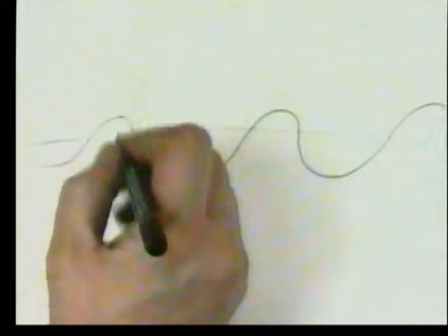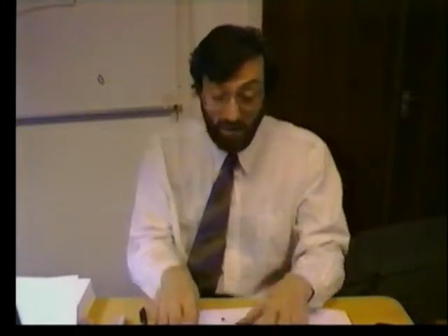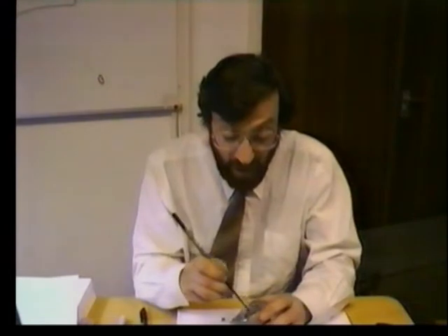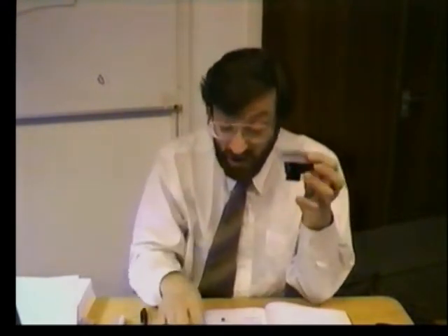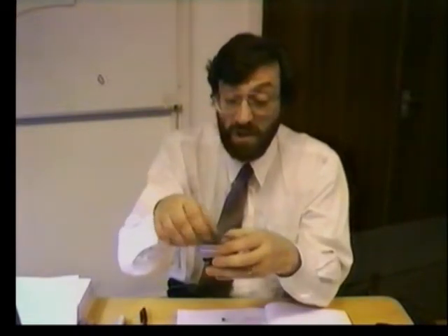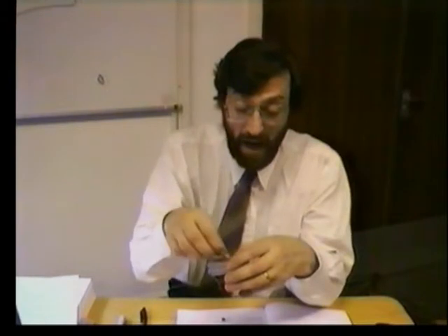Every time the magnet passes our pickup, we'll get a pulse. So in order for our computer to determine the volume of flow, all it has to do is count the pulses. Here we have a transducer. What is a transducer? It converts one measurand into another measurand.